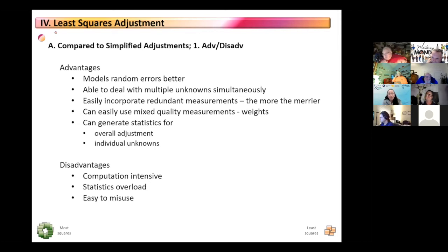Okay. I used to work for a local power company. We had to do 16 sets. So I took your 2 versus my 16, and it only picked up like 1 second. Yeah. And again, if you look at the FGCS specifications I showed last week for turning angles for a triangulation network, first order class 1 had 16 direct and reverse, third order had 2 direct and reverse. So exactly, it does make a difference, along with the resolution of the equipment you're dealing with.